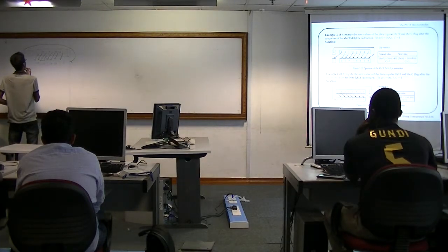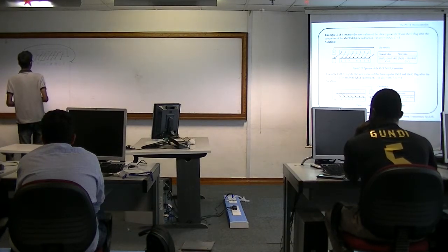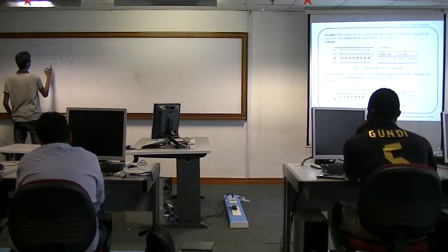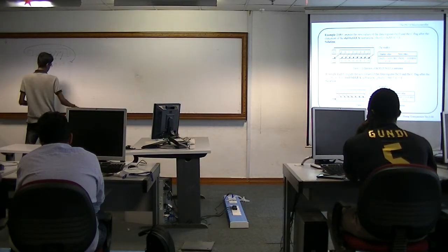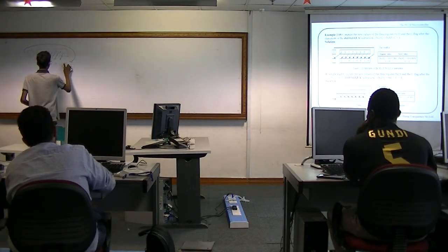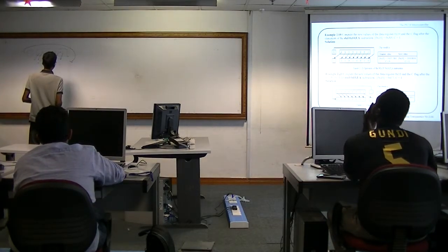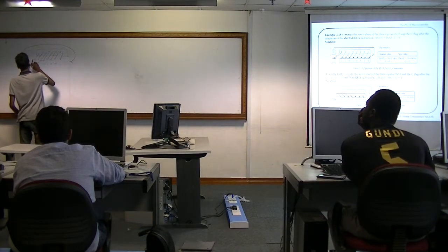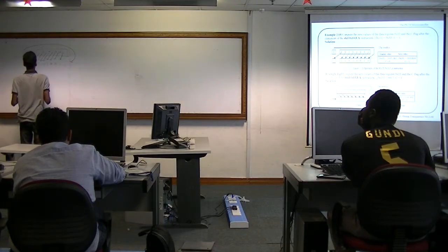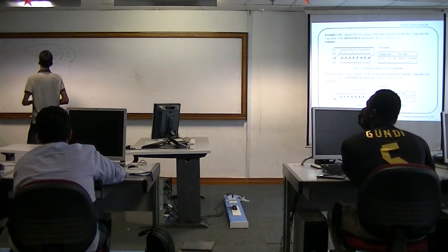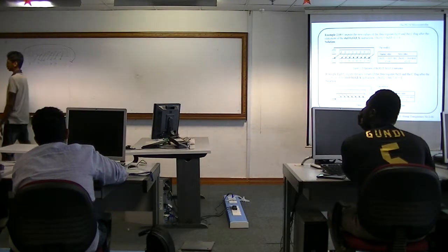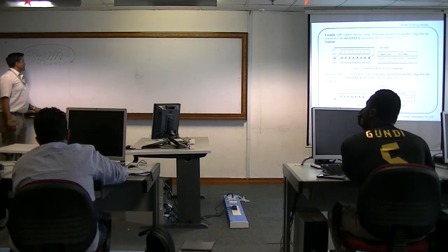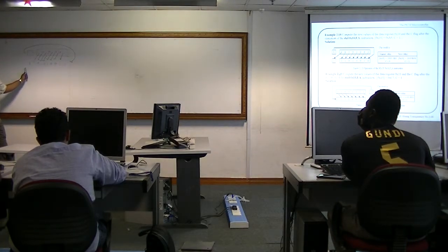So what's the new value? The last one should go back into the carry, right? Just put it a bit further, if you put it very close, you get confused. Not that one, that's correct. The most significant bit, that one put it a bit further. Yes, so you don't get confused. So what is the content of carry? The content of carry after you perform the rotate is 1.